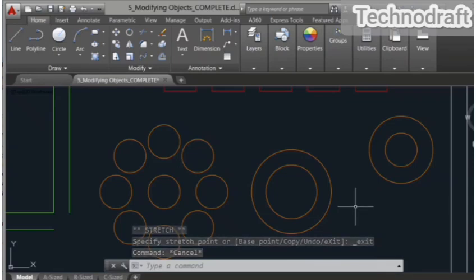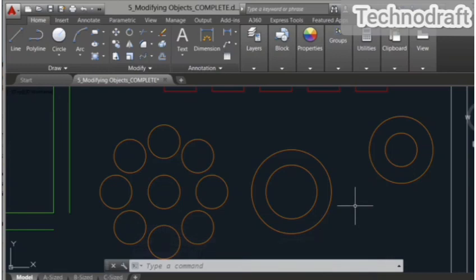Because on the AutoCAD Professional course, you do quite often get a question on grips and grips editing, but obviously I can't be specific about what type of work you are going to get. So practice using each of those grip editing methods and make sure that you are aware of how they all work and what they all do. Have a go at changing the base point, have a go at copying, have a go at doing something like the mirror using grips for example. So get into that grip editing and make sure that you get used to it, ready to become an AutoCAD professional.